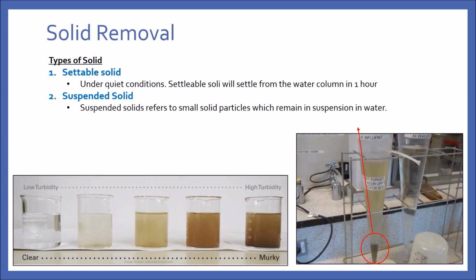Firstly, we need to understand the different types of solids that we are trying to remove from water. The first type of solids are what we call settleable solids. Settleable solids are defined as solids that will settle to the bottom of the water column within 1 hour. On the other hand, suspended solids refer to small solid particles which usually remain in suspension in water. In this lecture, we will be focusing on removing settleable solids.